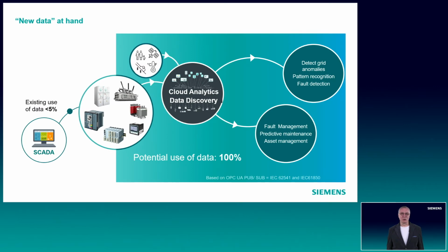How to access it without overloading the control center? The answer is using the cloud and the powerful data handling there. In addition, in the cloud, we can correlate with external data, as we did already in some of our projects. As one example, to predict damages on medium voltage distribution poles, we use data of snow level, flooding, bird population. Result? We could reduce incidents by 90% and saved a lot of maintenance budget.